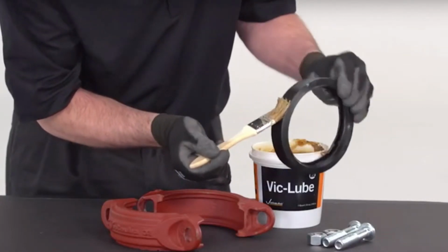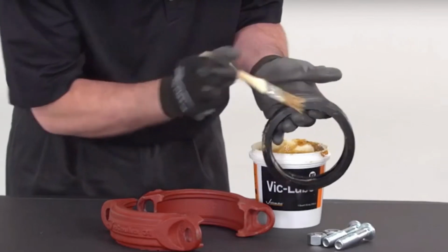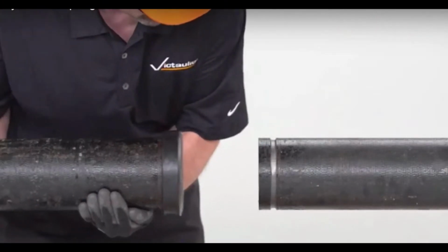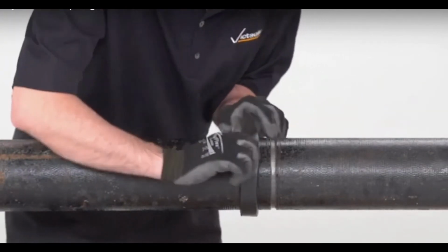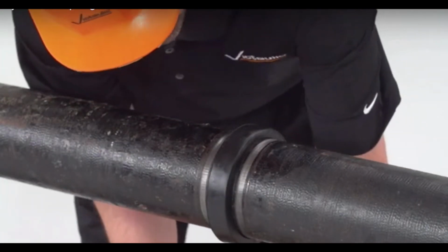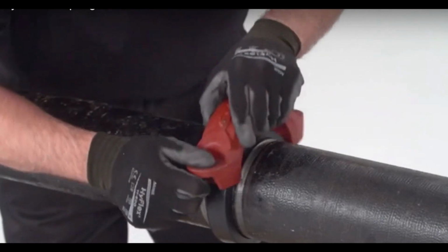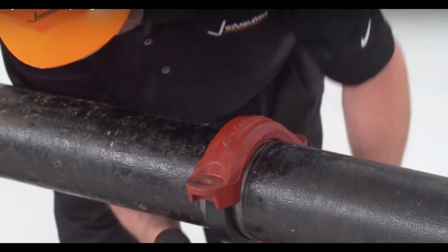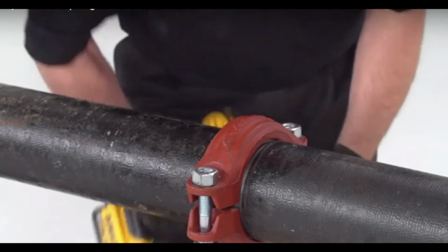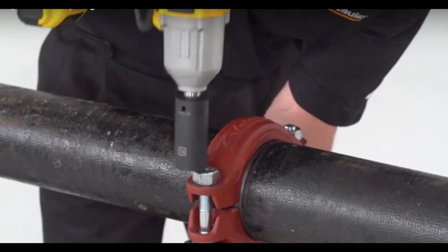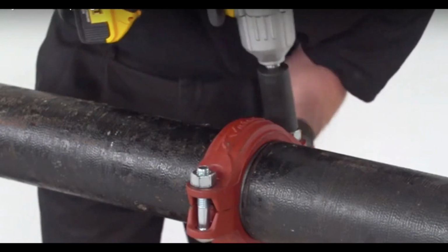With the roll groove made, here is how you would install a coupling to conjoin 2 pieces of pipe. Lube the gasket and the inside of the coupling. Slide your gasket over the piece of pipe completely. Butt the 2 ends of the pipe together firmly, and then slide your gasket over, exposing the 2 roll grooved ends. Then slide your coupling half on, slide the top half on, and the coupling will slide into the groove of the pipe, giving it the mechanical strength, and the gasket inside is your seal. Torque it to proper tension and move on to the next fitting.